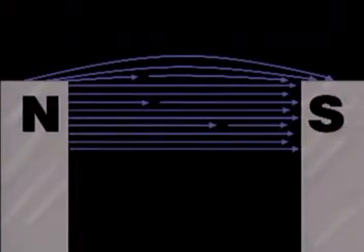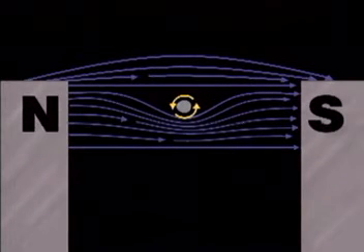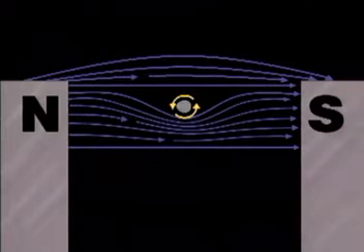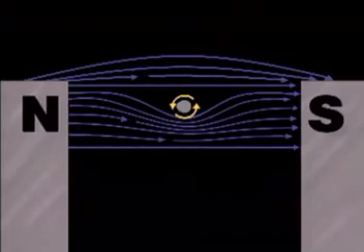The key to the operation of an electric motor is found in the interaction of the two magnetic fields, the stationary field and the moving coil. You'll remember that magnetic lines of force without any interference will follow the shortest path from the north to the south pole. However, the introduction of circular flux lines from the conductor prevents the magnetic flux lines from pursuing a straight path. This is because flux lines do not intersect. Instead, a complicated relationship develops between the two sets of flux lines.